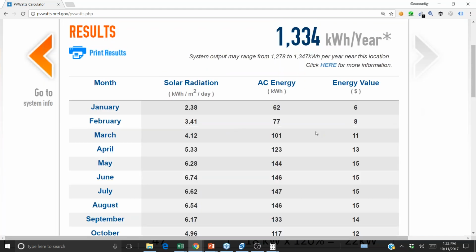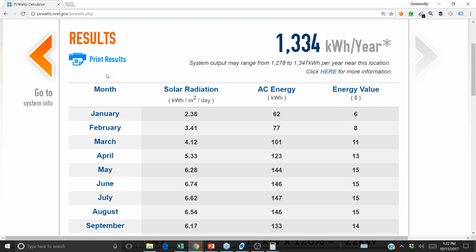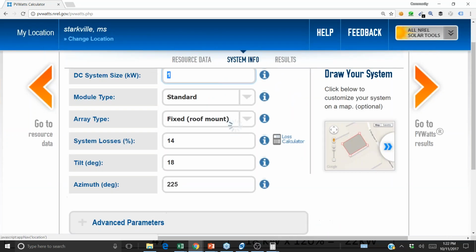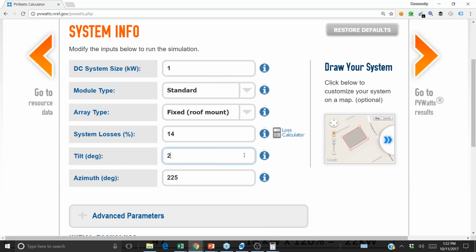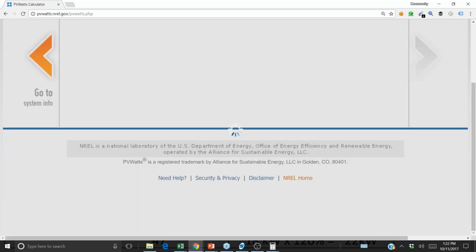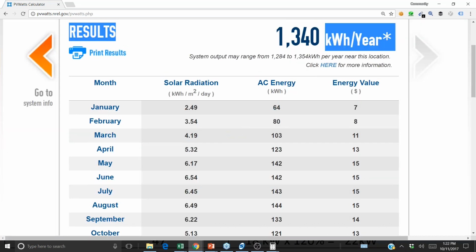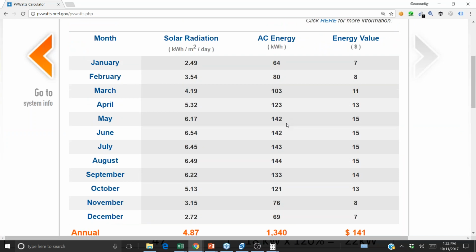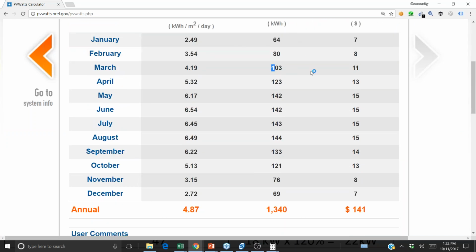as we talk about in other classes, minor deviations in the solar tilt angle, like going from south to southwest or going from a 4/12 roof pitch to a 5/12 roof pitch, that's hardly going to budge our actual performance. Going to a 26-degree tilt, like a 6/12, there's not much change in how much we produce a year. There may be some changes in how much we produce a month.